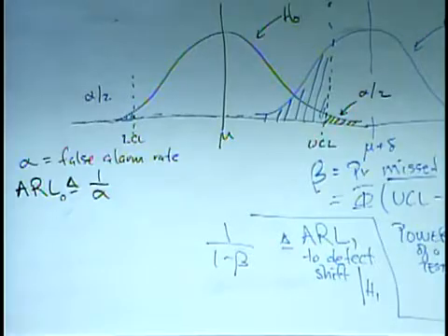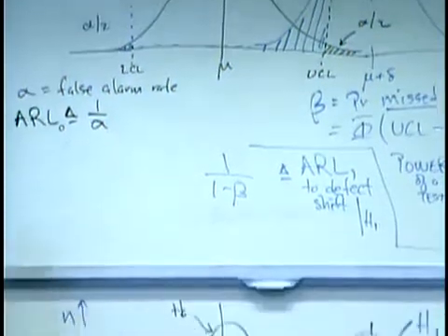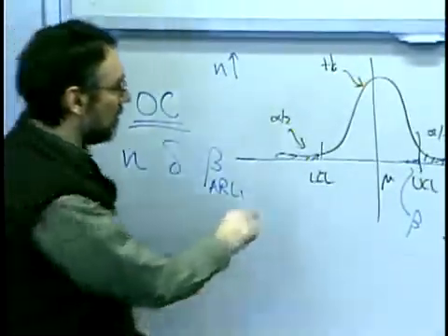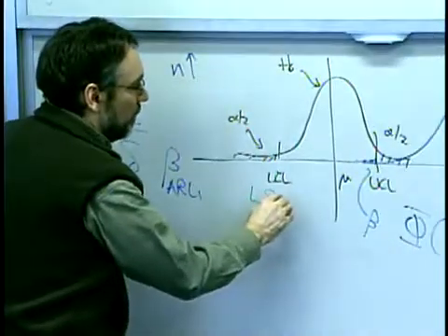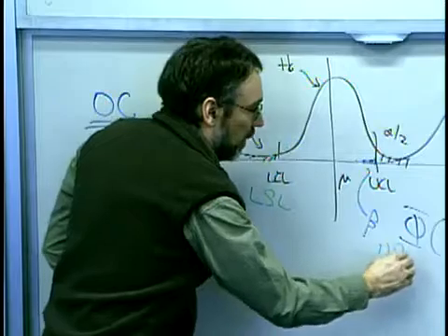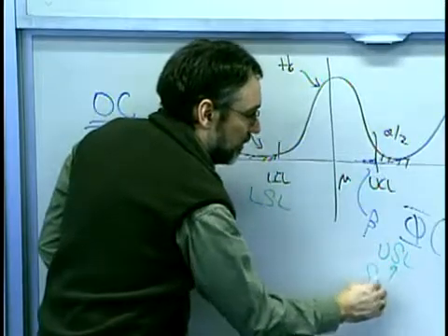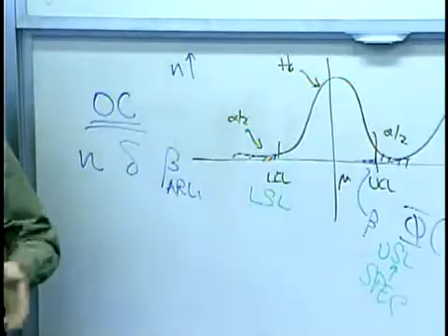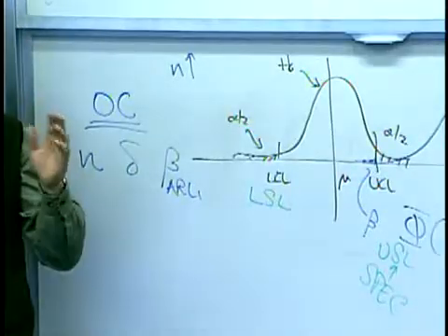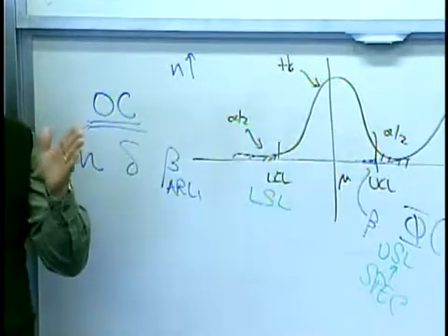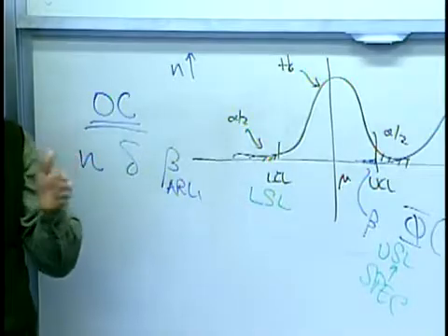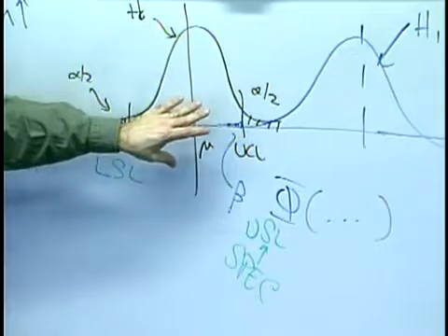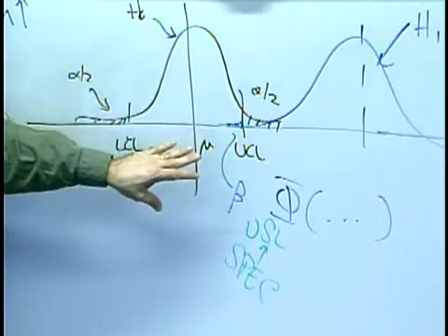And there's a really important thing that we'll get to in just a second, about process capability, where we start talking about upper and lower spec limits, which is related to the notion of where the part's property really needs to be for it to function correctly. And those are very different than control limits, but often confused.